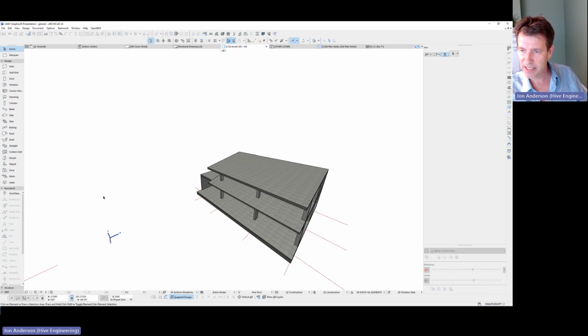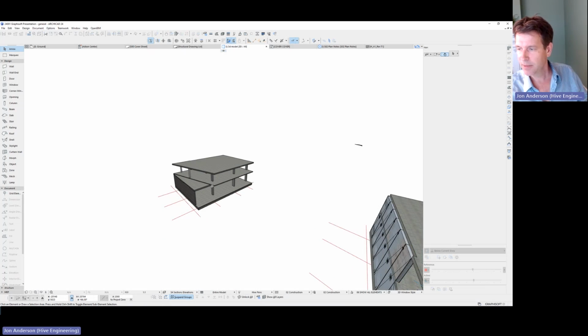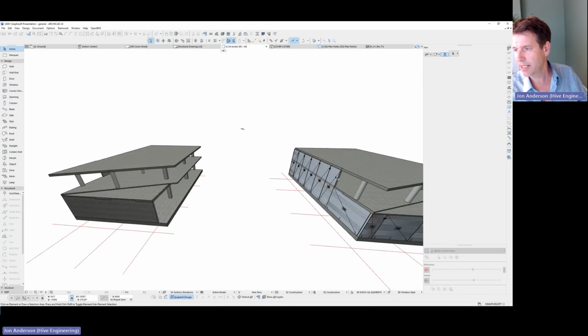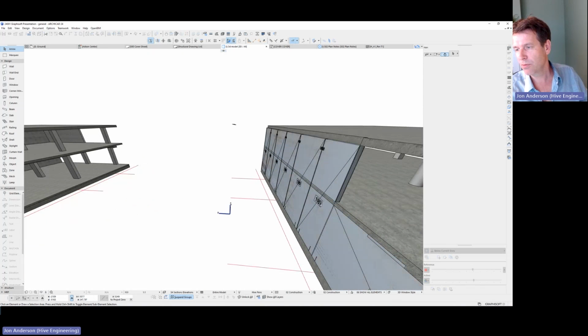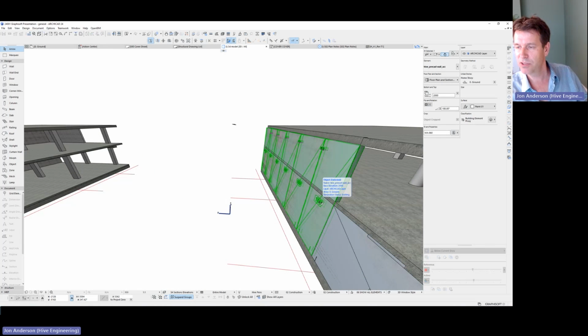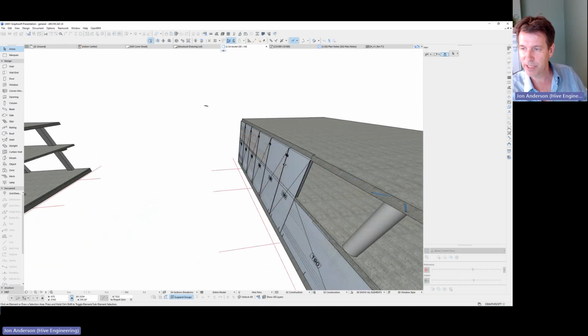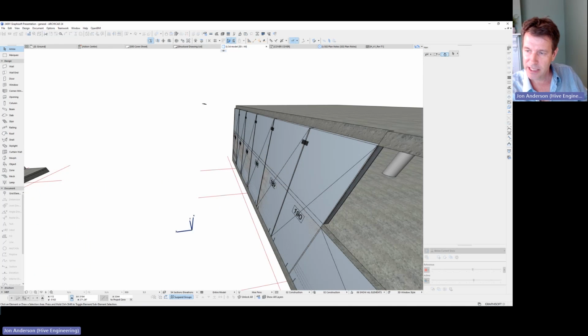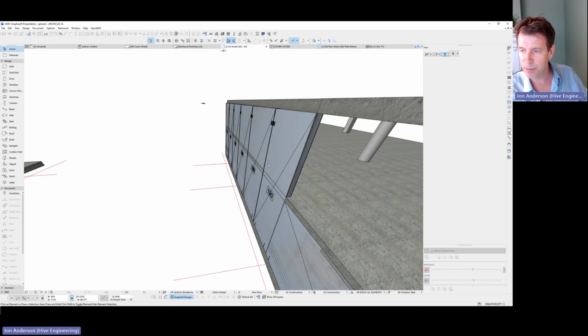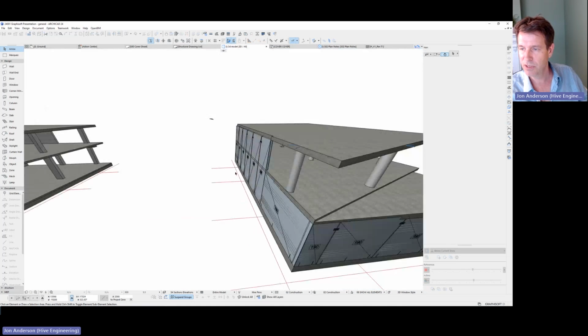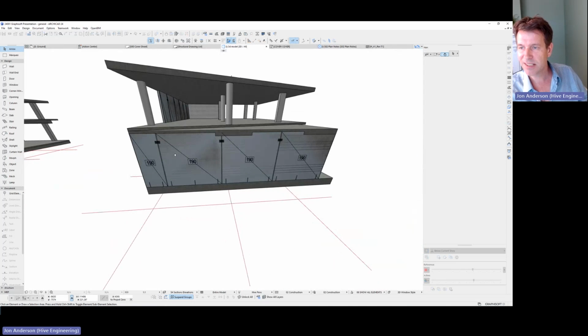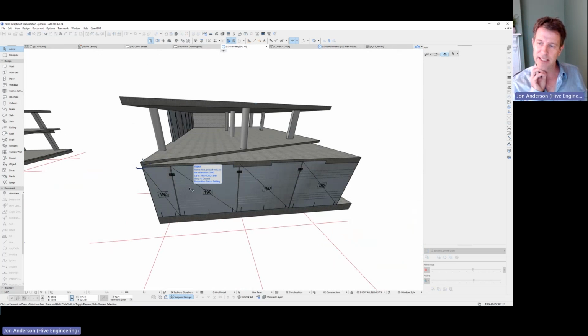If I take that simple little structure again, you can attach things like accessories, which can read the wall thickness. This is one that I would use for nominating precast concrete panels. And then when you show them on elevation, they're all labeled, which is really fast, particularly if you're documenting a building with lots of precast in it.